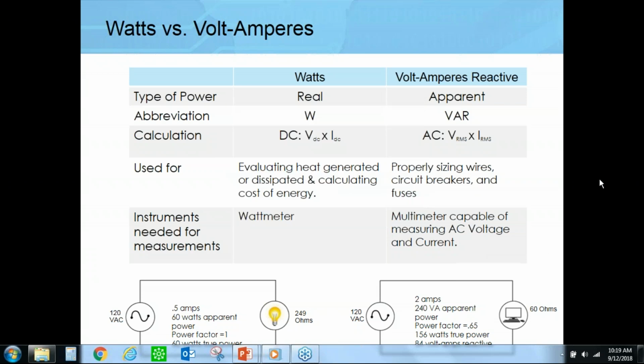All right. So how do you measure watts? You need to measure watts using a watt meter. Some of the power supplies that are out in the market already have these meters built in. They will have a real power component built into it. They will have an apparent power measurement done with voltage RMS and current RMS, and then they also measure the true power requirement.